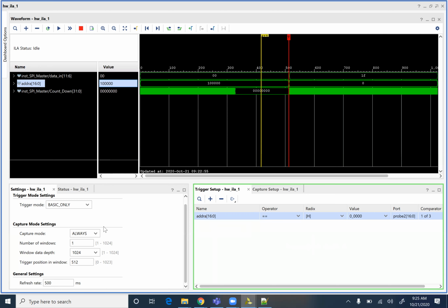So the two-state method is where the states control the clock. So you're going to have a state where the clock is set up and the data is set up, and then a state where it's all clocked in. So it looks like this device is rising edge triggered, whereas the SPI one was falling edge. So setting up the clock involves setting it low.